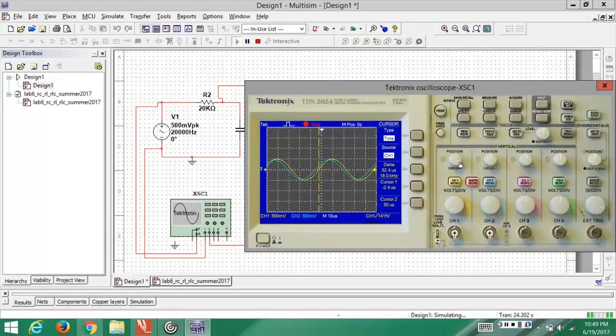If you look at the yellow waveform, I think it started from here. Wherever the cursor intersects the yellow waveform is the place where I think that cycle started. The menu says cursor 1 is at -2 microseconds, so I can say that this cycle started at -2 microseconds.